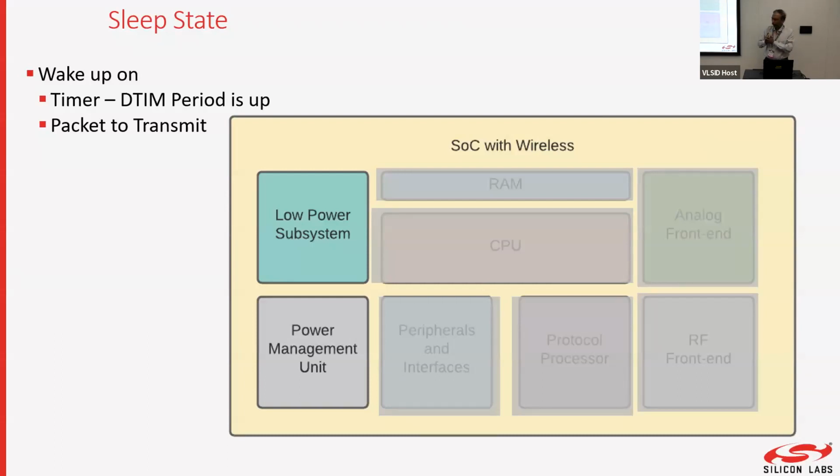Now, here is where there's an important concept of energy being equal to power multiplied by time. The less time you use in a non-productive state, the more energy you save. So when you wake up and you find that your connection state is gone, you have to give your Wi-Fi password, you have to establish your secret keys, you have to do your 4-way handshake. All that takes a few milliseconds. And during that millisecond, you can neither transmit nor receive. That is dead interval. And during those few milliseconds, you are transmitting, you're receiving, everything is on unproductively.